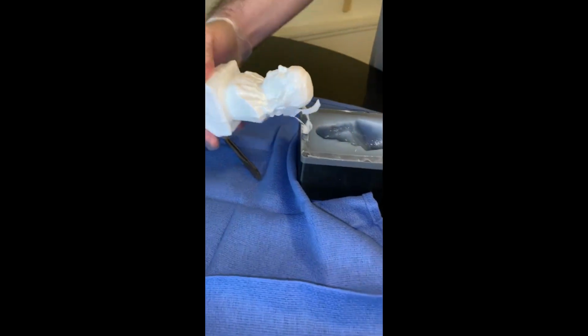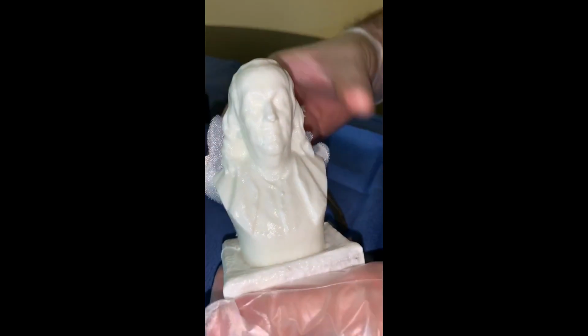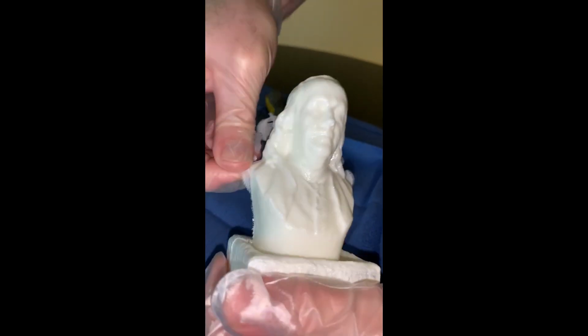Now the third type of mold is also a two-piece mold, but the parting line is non-planar. Now here are two examples of parts that you might need this for. So here we have a bowl. So a two-piece mold for this, we can't use a planar mold because we need the interior surface to come up here above the parting line. So there's no single plane that we could pick that would divide it correctly.